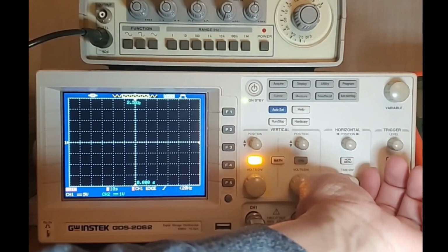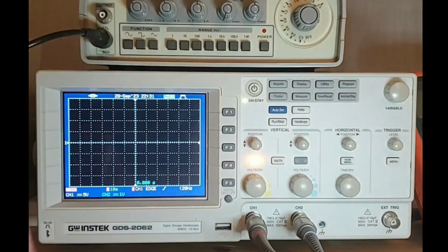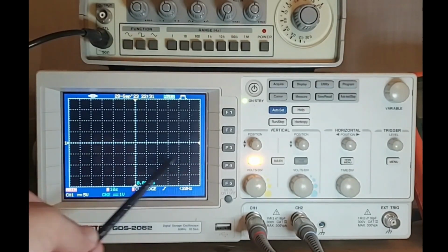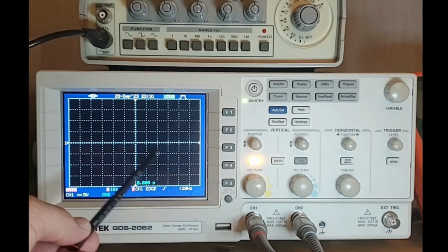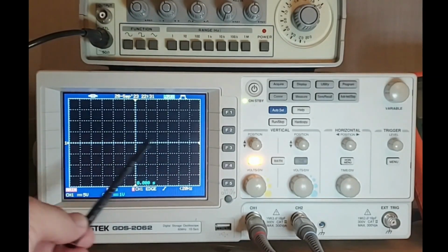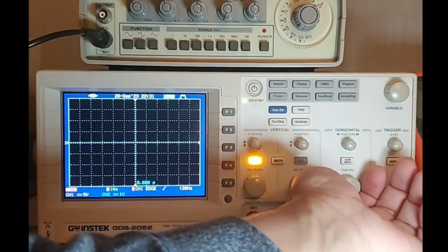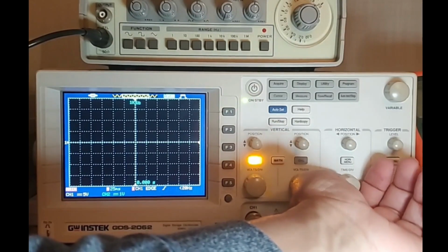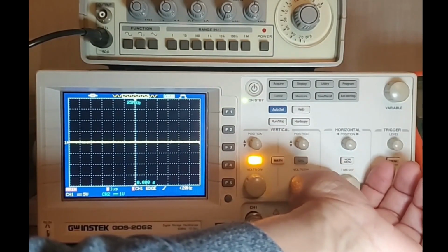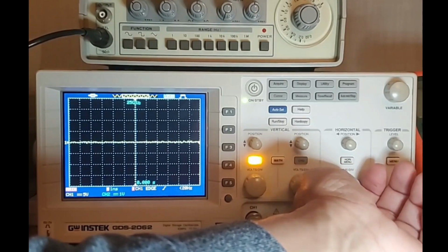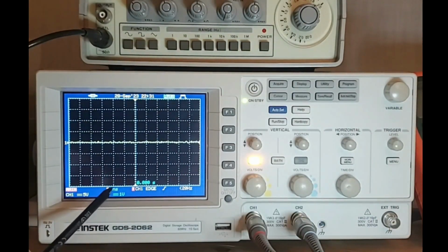So for example, if I bring it to maximum, it's 10 seconds. So now each division is 10 seconds, and it will take the waveform 10 seconds to cross one division. And that's a very long time. You can see I have 12 divisions, so it will be 120 seconds for me to get one trace. So that's the maximum time per division that we can have, and the minimum in this case is 1 nanosecond. 1 nanosecond is 10 to the minus 9 second. It's a very, very small period of time.